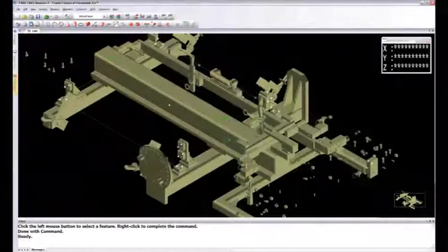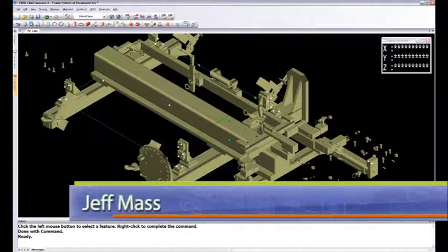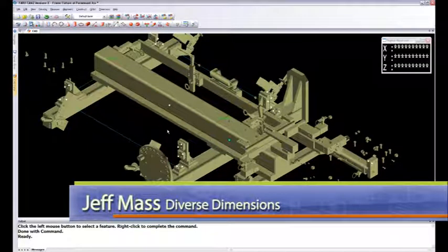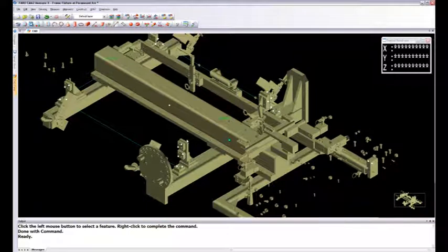Well, I'm right in the middle of this measurement session here. Just completed the initial measurement on this fixture. This client has got some datum pins and pads and some rests and stops all over this fixture that are used to locate parts before they actually assemble them together. And what we're going to do is add some shims or take some shims out and make this as close to nominal as we can.